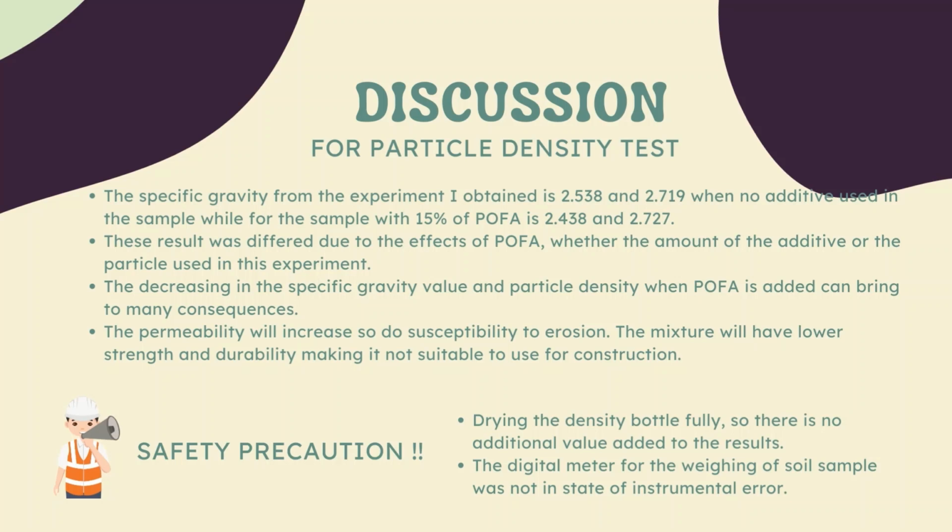The decrease in the specific gravity value and particle density when POFA is added can bring too many consequences. The permeability will increase, and so will the susceptibility to erosion. The mixture will have lower strength and durability, making it not suitable for any construction.